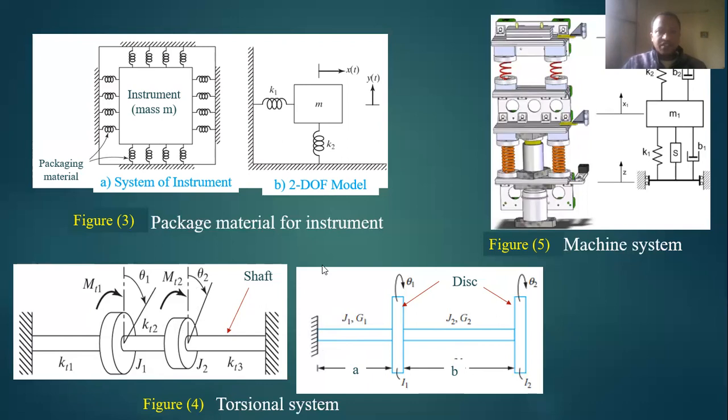And also here, this is a cantilever form; this one is fixed at both ends, and this one is free at one end and fixed at the other. So we can represent a 2 degree of freedom system. When we talk about degree of freedom, we must consider the number of masses. And in most cases, we consider discrete or lumped mass on the system. So this is a 2 degree of freedom system.